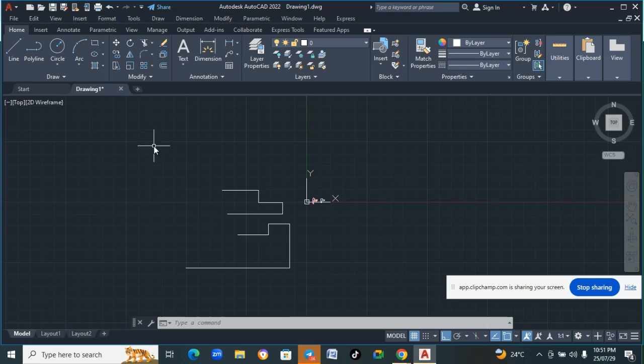Then also watch what I'm going to show you right now. When you activate the line command, watch the command line. Let me start afresh. The command line is empty. If I click and activate the line command, it tells you, number one, that the line command is active.